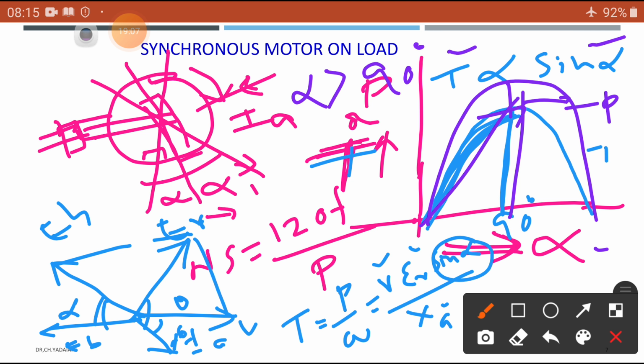So synchronous motor hunting may have these reasons: one, the varying of the load on the synchronous motor, and two, the supply frequency variation itself. So these are the things that produce hunting. Okay, from this, we have concluded before going to the analysis.